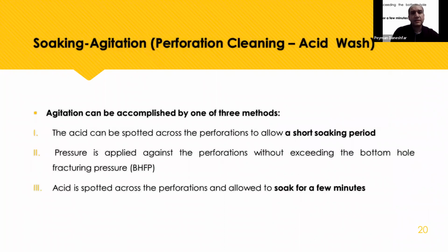And what is an acid wash that we use every time? After the well operation is okay, check the formation damage, or if you have mud filtrate or something in the well, or for wellbore cleaning, we use the acid wash. We inject the acid into the well. We have three types. One of them is that we clean up the acid as quickly as possible. Another one is with some additive added to the acid.